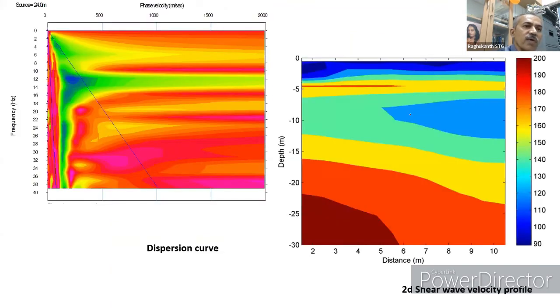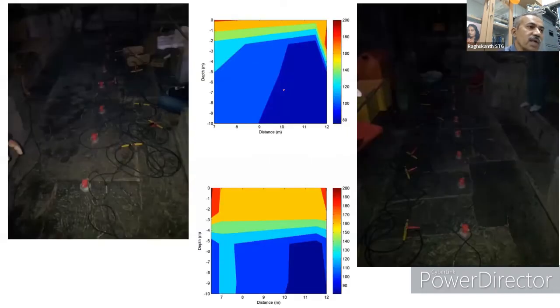And we get these types of graphs, and then we get this type of figures itself. So you can see this is the foundation. You can easily find out at a depth of 30 meters, say, whether there are any cracks or something. So we can easily get the results from this itself. But it is very challenging to interpret these results.